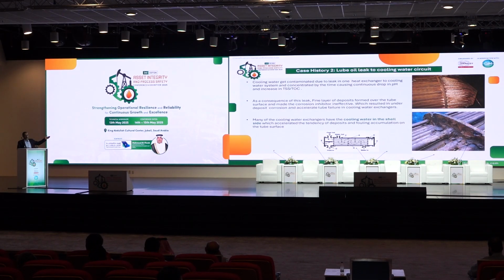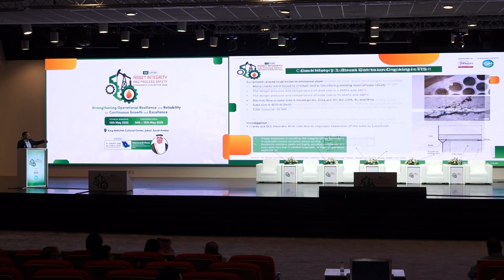And this is related to allocating the cooling water in the shell side. As you can see, the cooling water in the shell side, after some time, can impact the shell side by high deposition rate and under deposit corrosion, impacting the lifetime of the heat exchanger.